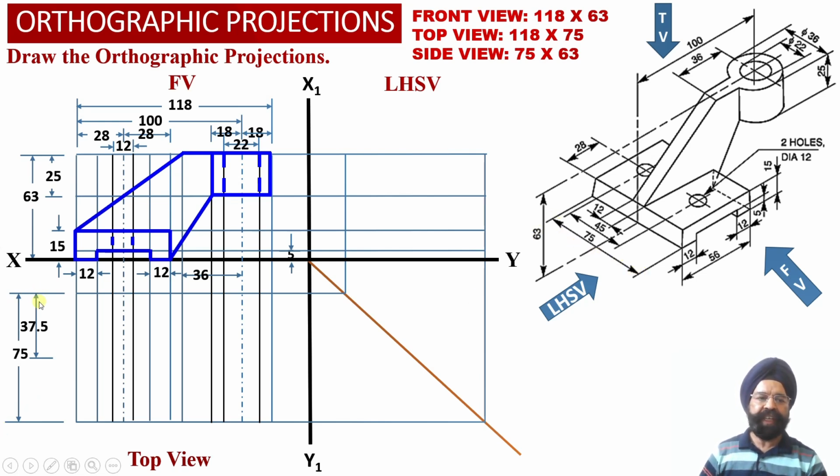So if we take a distance of 37.5 millimeter from the rear surface or from the front surface of the solid, a center horizontal projection line is obtained into the top view projections, and we have transferred this center projection line from the top view projections into the left hand side view projections over here using this transfer line.